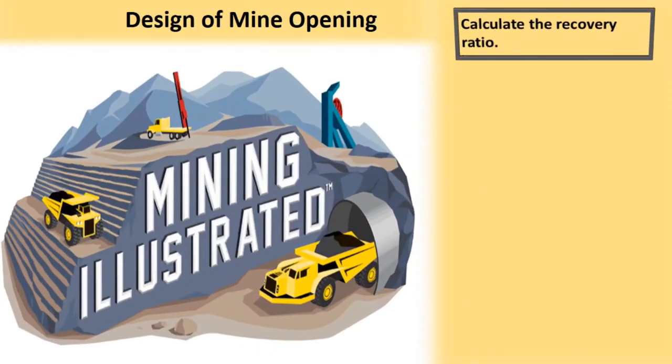The recovery ratio formula is opening width over opening width plus the pillar width. And the value of the recovery ratio is 0.1667 and the recovery ratio percentage is 16.67%.